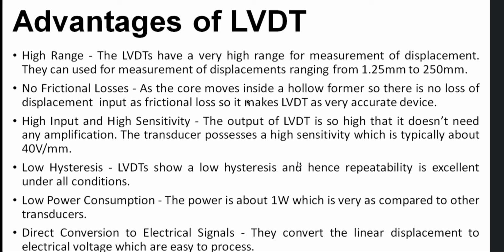Then low hysteresis. LVDT shows a low hysteresis and hence repeatability is excellent under all conditions. The next point is low power consumption. The power is about 1 watt, which is very low compared to the other transducers. The last point is direct conversion to electrical signals. They convert the linear displacement to electrical voltage, which is easy to process.